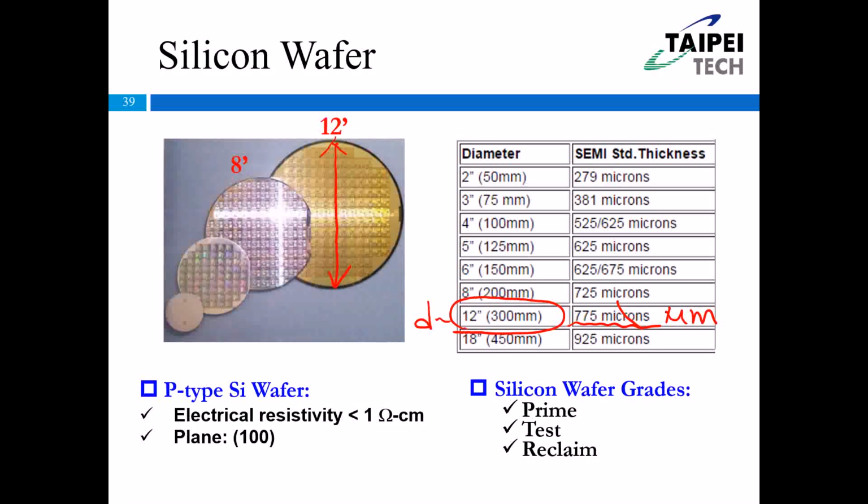You know, all of this semiconductor processing is not done by humans. It's not done by me or by you. It's done by the facility, by the processing tool itself automatically, okay? So today we need to use the robotic arm, 机械手臂, to transfer the silicon wafer from one tool to another. So we need to make sure the thickness is around 775 micrometers so the silicon wafer will not have breakage or deformation.